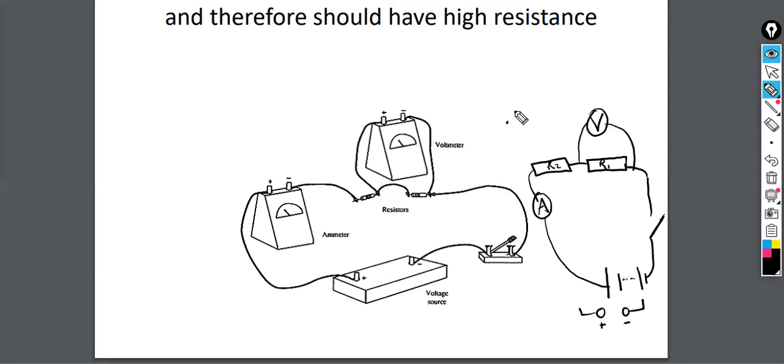Remember the other symbol for a resistor is this one right here. We have a straight wire where we want the charge to flow through, then we get to a resistor where we're resisting the flow of charge, and the charges get slowed down. Remember, they're just pieces of metal. For the metal here, I = nAvq, the current goes through. We have a piece of metal with number density n, and it has current I equal to that number density times the cross-sectional area times the mean drift velocity times the charge. The resisting wire has an equation governing it: resistivity equals resistance times area divided by length.